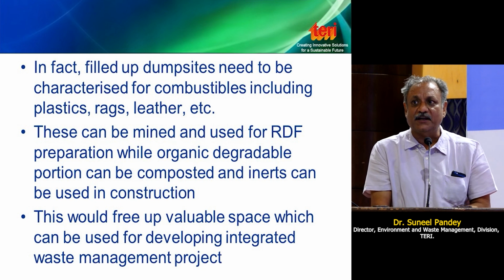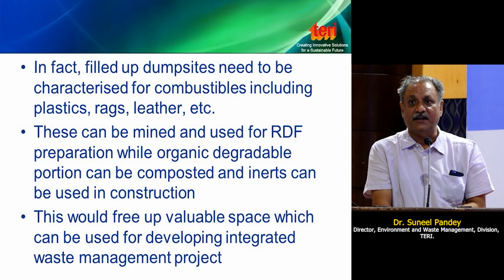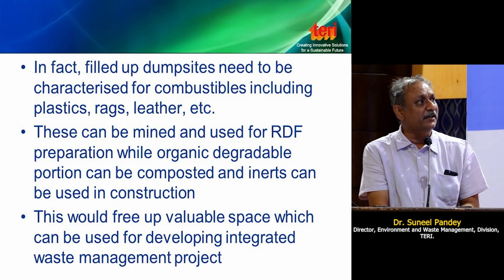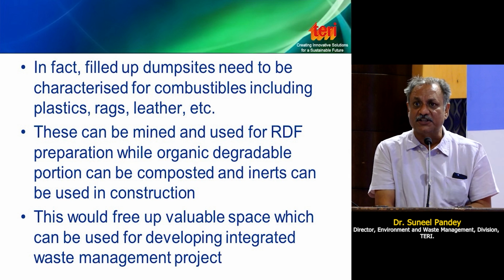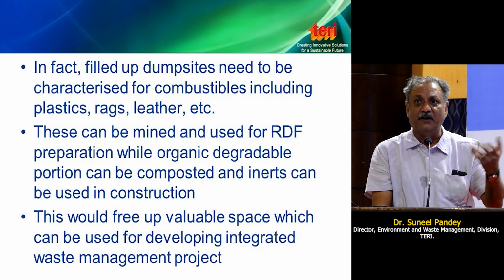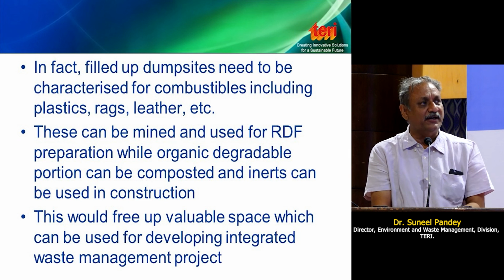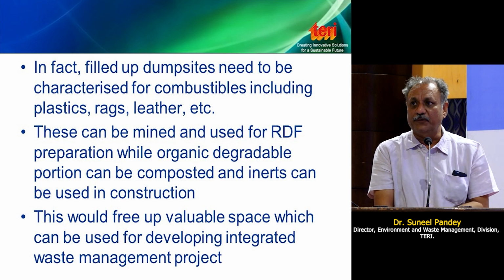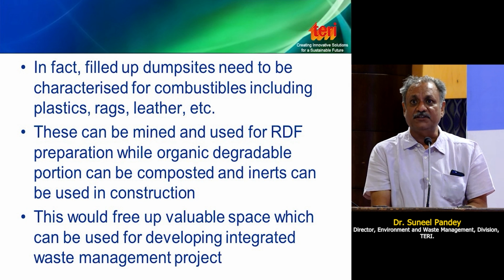A lot of action is happening in the country for remediation and redevelopment of the landfills which were created as dump sites earlier, and how these landfills can be mined out. Different materials can be used: combustible materials for converting into RDF, soil-like material for soil conditioners, and if there is any green waste left, then in compost and landfill. These landfills are now being mined and redeveloped by the Government of India, and it is proposed that an integrated waste management plan would be set up in such created space, which would help in managing the waste in a scientific manner in future.